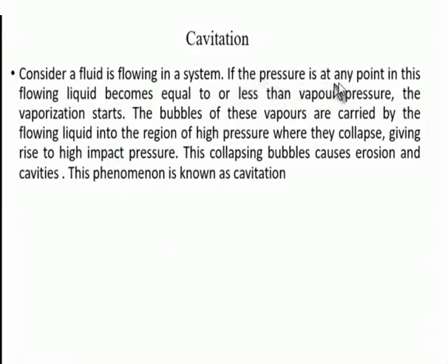If the pressure at any point in this flowing liquid becomes equal to or less than the vapor pressure, vaporization starts. At that time, the bubbles of this vapor are carried by the flowing fluid into a region of high pressure, where they collapse.